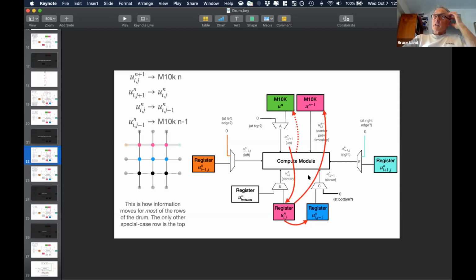One other strategy I've seen in the past is to start by making a list of registers and memory blocks in one direction and then cycles in the other direction. And in every block, fill in whether there needs to be a read, a write, or both for each different memory, so that you can make sure that you never ask for more than one at a time. Okay. That's just colored pencils on paper kind of work.